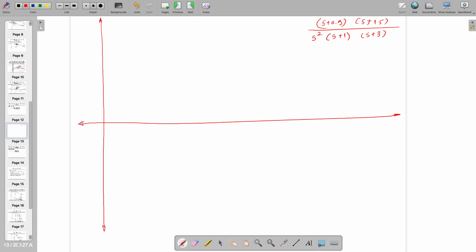So our strategy, when this system is given to you, is that you are going to write down all the poles and zeros. Let's write down poles and zeros. So poles are 0, 0, minus 1, minus 3, and minus 1.5. When you find these poles and zeros, you should not start drawing the Bode plot, but you have to order them. First, the first two are zeros. Can you see? These two are the poles, two poles.